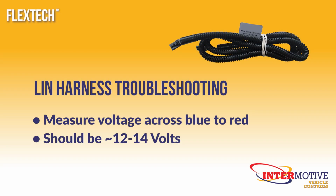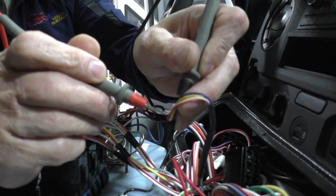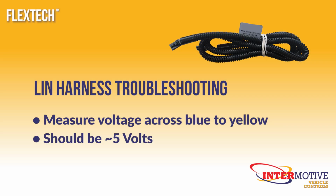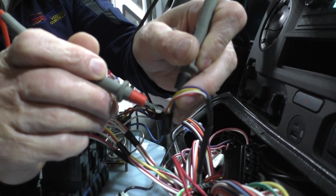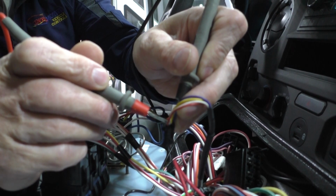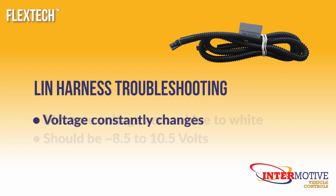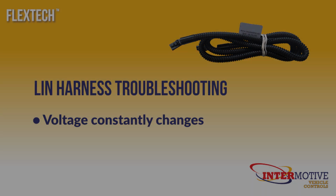It should read between 12 to 14 volts. Measure the voltage across the blue wire to the yellow wire. It should read approximately 5 volts. Measure the voltage across the blue wire to the white wire. It should read between 8.5 to 10.5 volts. The voltage is constantly changing, as it is a communication signal.